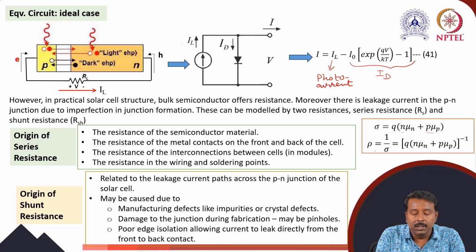And if in the PN junction there is some bypass, that is a short resistive path, then the physics whatever we have discussed for carrier motion, that is under drift, under diffusion, may be violated in that case, and current may follow some low resistive path in the junction.